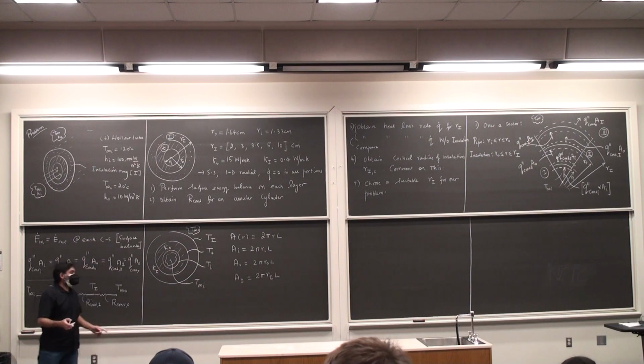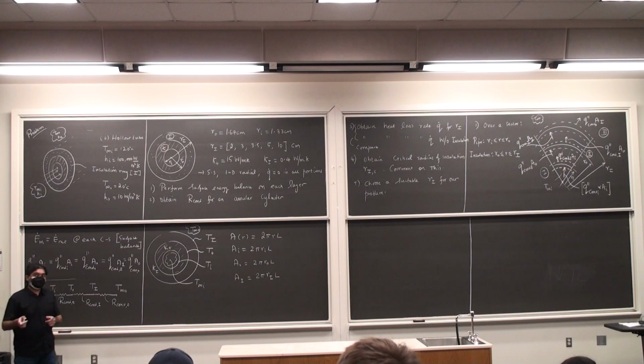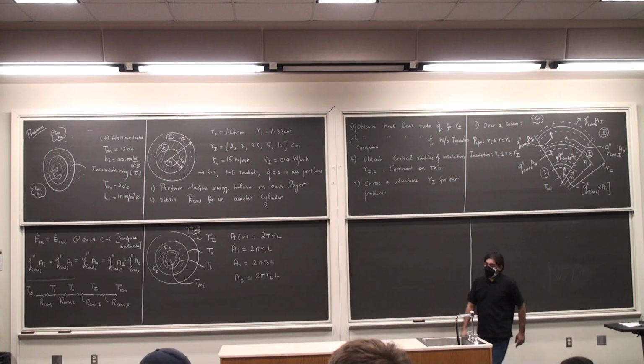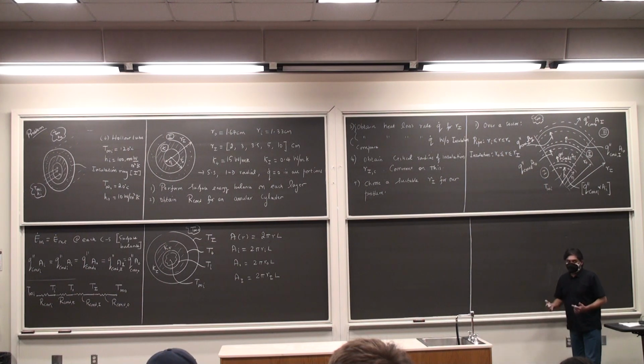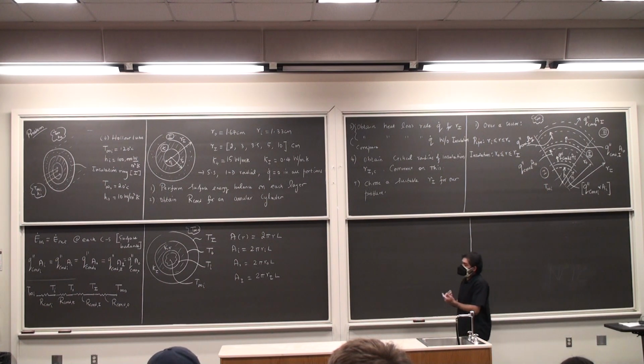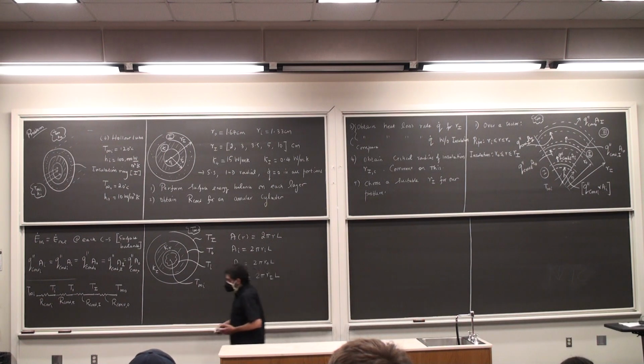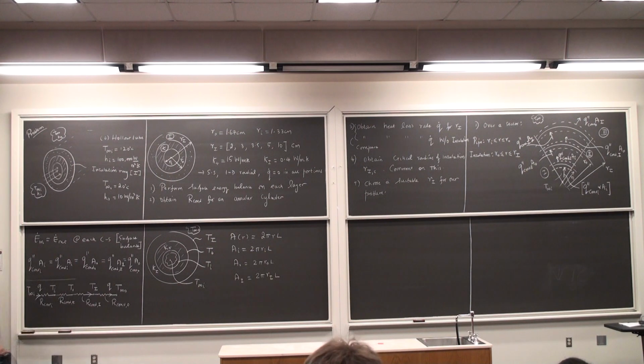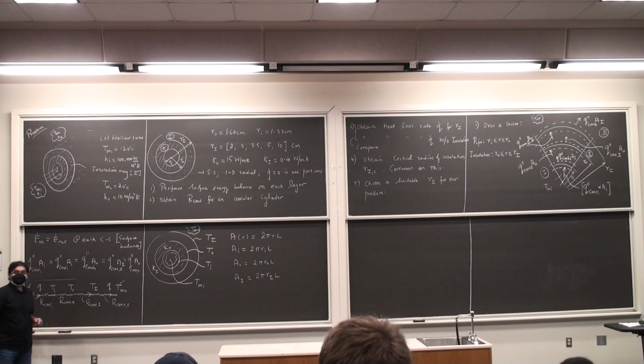It is highly possible that we may not complete this problem today, so we'll come back on Monday and complete it. Before I go to the next step, which is to actually calculate the heat transfer rate, I need to write down Q. It is very obvious to recognize from the problem: I am given T infinity I, which is 120 degrees Celsius, and T infinity naught, which is 20 degrees Celsius.